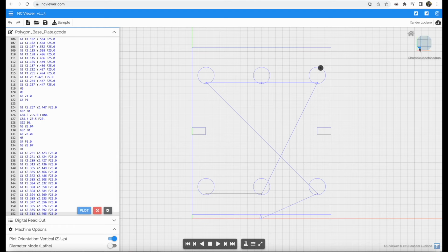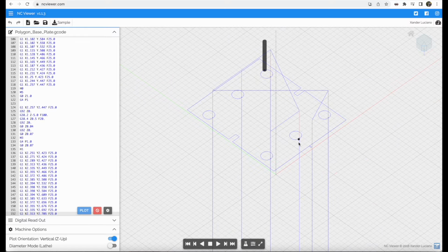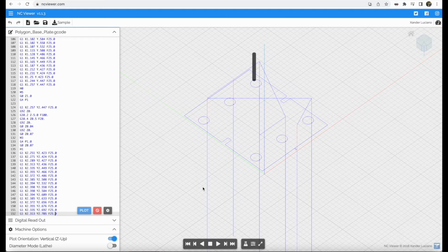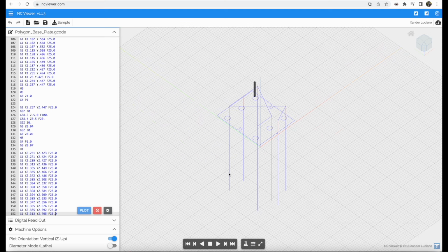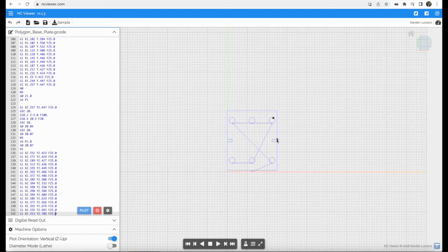I'm going to look from one of the side angles so that you can see the G code that's generated for the plasma table uses a torch height control, which has these G code paths that they're not easy to understand, but what it's actually going to do is drop the torch until it detects the metal, and then it's going to move up to a desired height. So that's why it's got these paths that won't actually descend into the part.